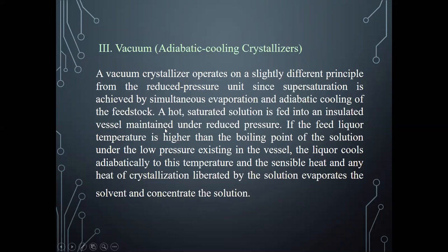A hot saturated solution is fed into an insulated vessel maintained under reduced pressure. If the feed liquor temperature is higher than the boiling point of the solution under the low pressure existing in the vessel, the liquor cools adiabatically to this temperature, and the sensible heat and any heat of crystallization liberated by the solution evaporates the solvent and concentrates the solution in the process.